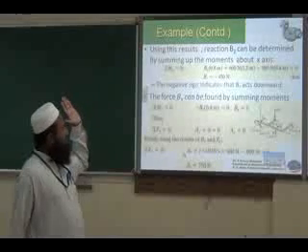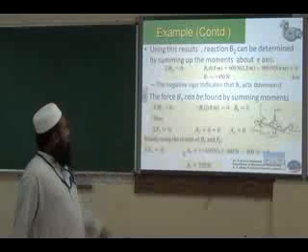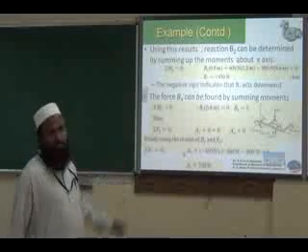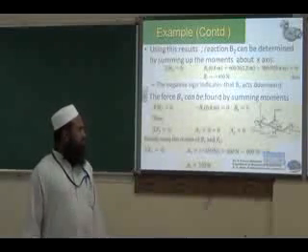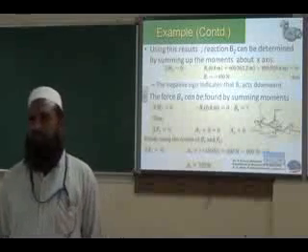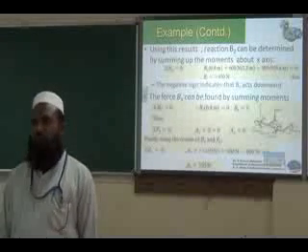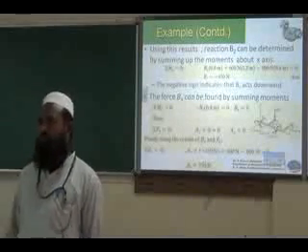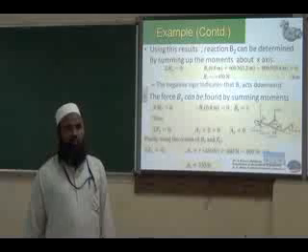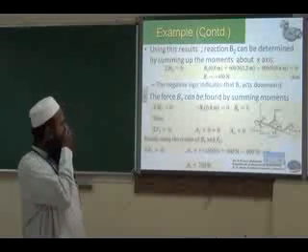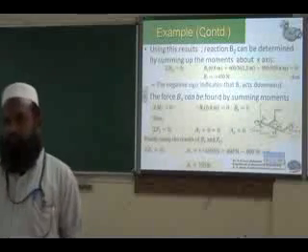Okay, so first we take sigma fx, then taking moment about x, moment about z, then using sigma fx and sigma fz equation, we found the other unknowns. You can use moment equations also instead of force equation, but force equation is simpler. We need not multiply it by the perpendicular distance, so it will be simpler. That is why we prefer force equation if it is possible to find by force equation. So we got all the unknowns. So if you have any doubt, you can ask.